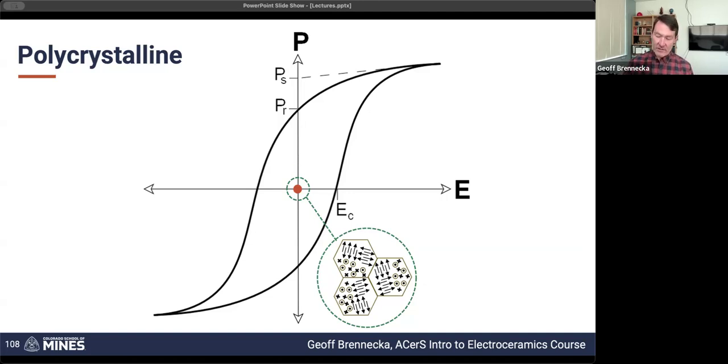within each grain. And then you'll notice there's some coordination across grain boundaries, and exactly how much of that applies depends upon the nature of the grain boundary and the magnitude of the spontaneous polarization and all sorts of factors. But it is fun to see domains that actually cross grain boundaries, because when you get to the end of a domain at a grain boundary, there's still going to be a surface charge there, and that surface charge will influence the domains on the other side of the boundary.